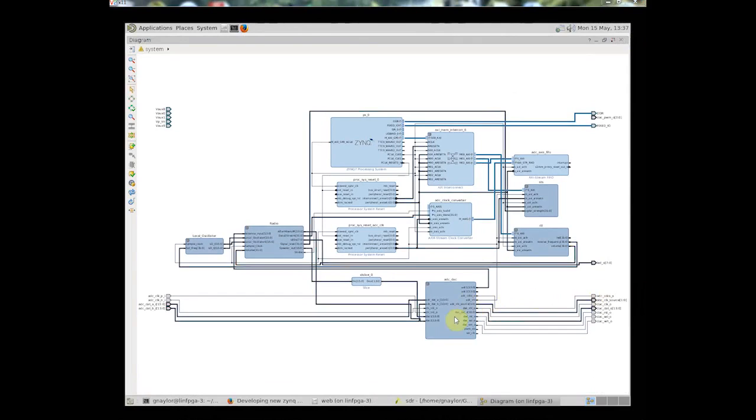So to recap our design for a software-defined radio, a couple of tips: when we passed analog data in this radio design, sometimes we had unsigned values and sometimes signed. It's very important that the input to blocks is correctly specified, because if you treat unsigned as signed, then you're going to get some strange results, and your signal will be quite corrupted.